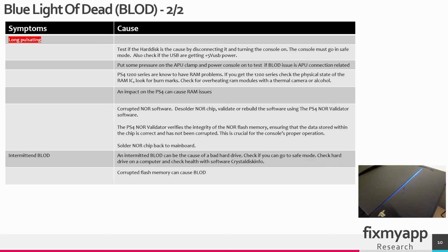Also, if you drop the PlayStation, it can cause RAM issues or APU issues because, again, solder joints could be broken or traces ripped, and that can also cause a long pulsating blue light of death. Corrupted firmware is also a cause of a blue light of death.